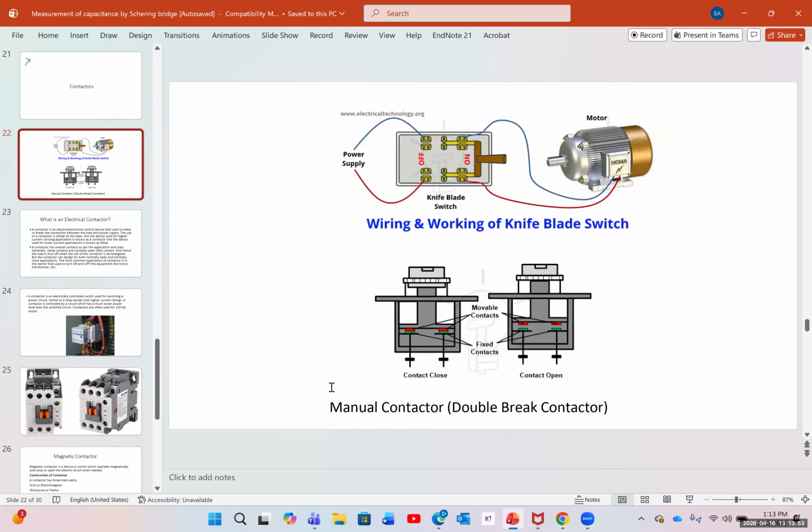The way a contactor works is we have a magnetic coil here, and when we power it, it's going to attract a plate, and then you have the connections. And on top of that coil, you have a spring. When you de-energize it or turn it off, the spring is going to pull it back, and you would disconnect.